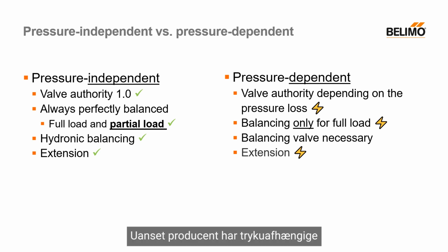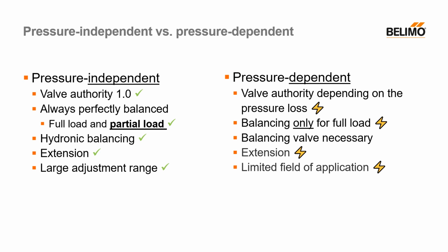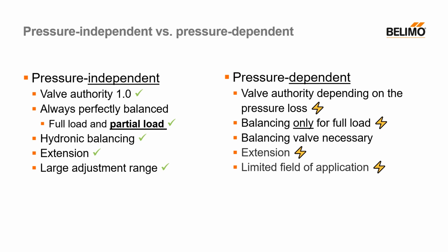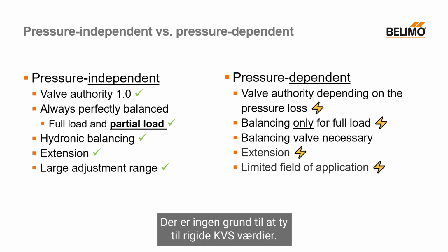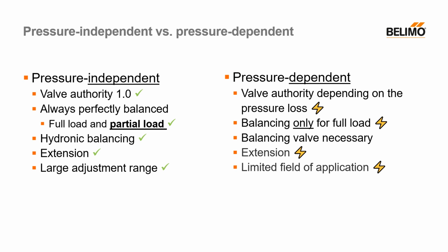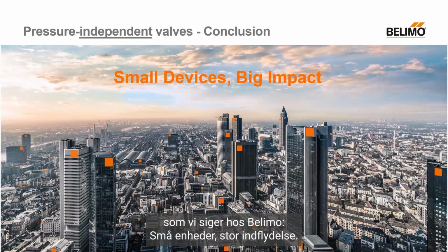Regardless of the manufacturer, pressure-independent valves always have a very broad field of application. The advantage is that one valve can cover many requirements. There is no need to resort to rigid KVS values, as with pressure-dependent valves. The bottom line? As we say at Belimo, small devices, big impact.